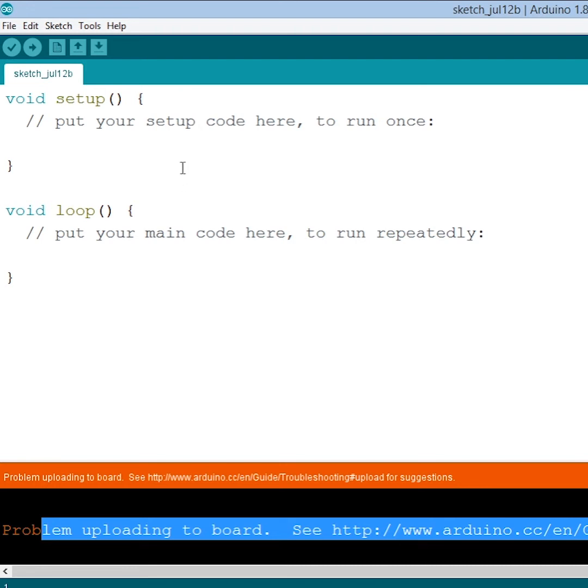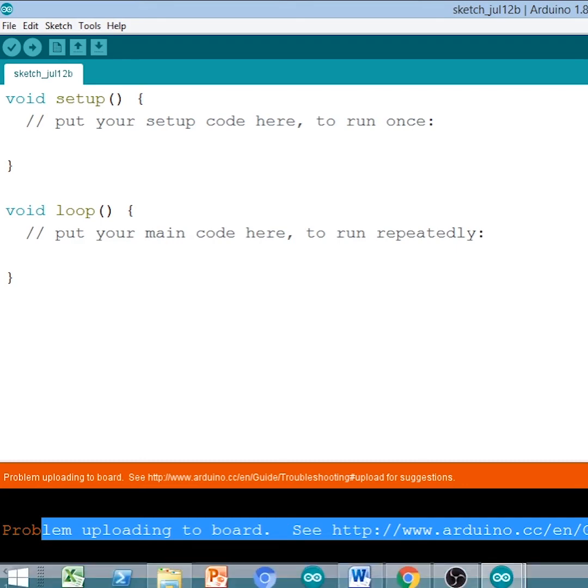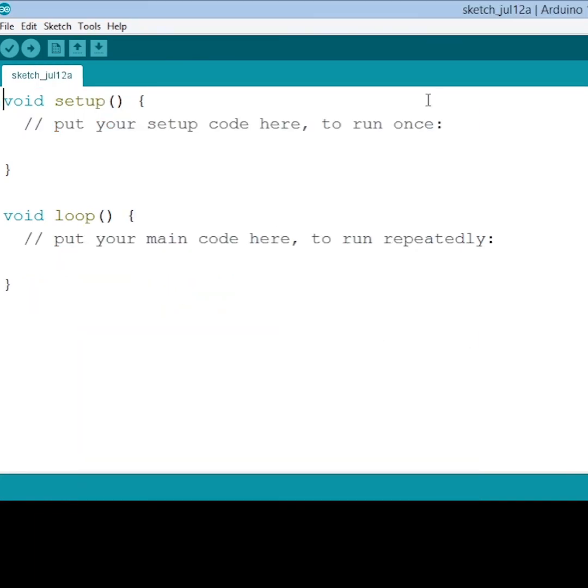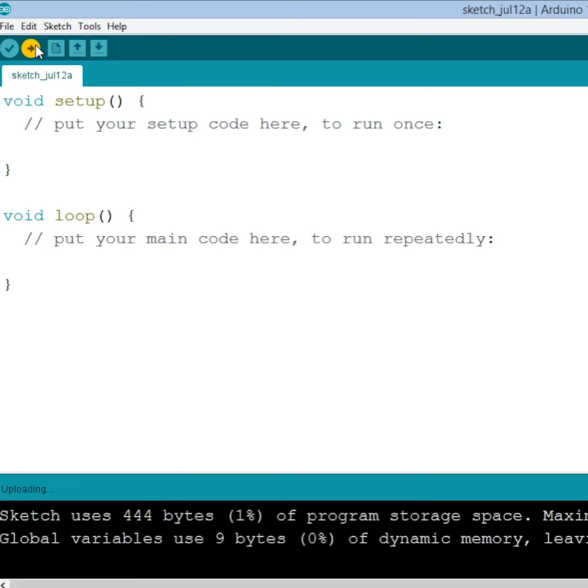The other type of error we're gonna see is generated when pin 0 and 1 of the Arduino are being engaged. When any of these two is engaged and we are trying to upload code to the Arduino board, this is gonna generate some error. Before the error is generated, it's gonna take time for the Arduino to try to compile and sync, so the error is gonna take longer to appear. We might even think that the board is not working, as the time taken is very long.